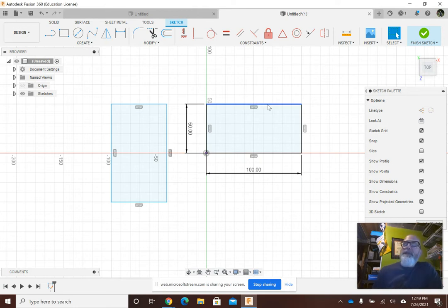So what happens if you're creating a design, working along, you've got your mouse and you accidentally do that? Got a problem now, don't I? So I've changed this value. All right. That's why we use, as often as we can, our constraints constraining the size of the rectangle.